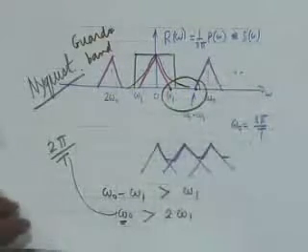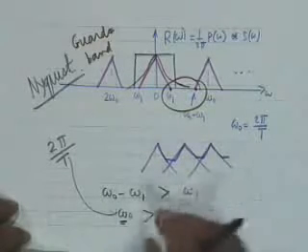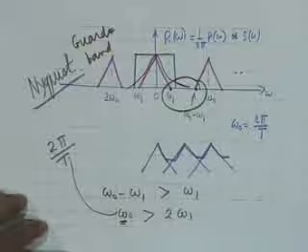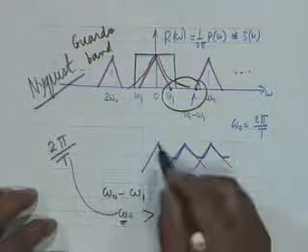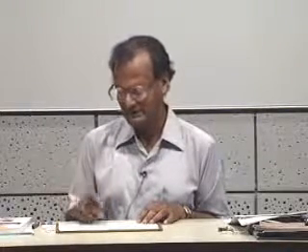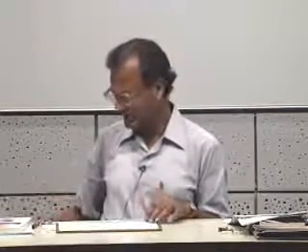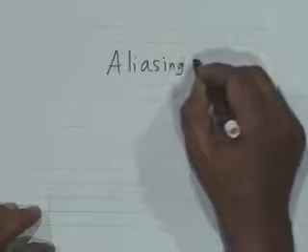But if you are not too careful about your system design, you may ignore Nyquist's band or Nyquist restriction. If you do, then obviously your spectrum shall be distorted, and there is no way that you can recover the original spectrum or the original signal or the message from the transmitted sampled version of the message. And the distortion that arises is known by the name of aliasing distortion. You shall learn more about this later.